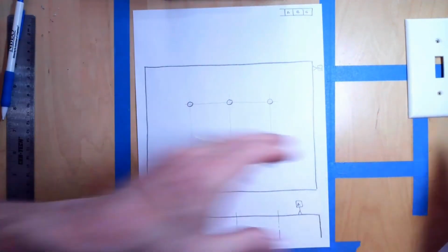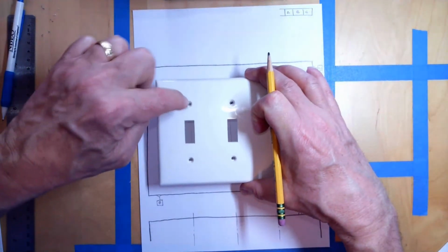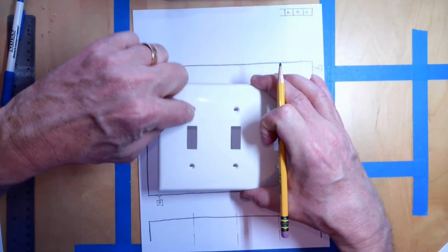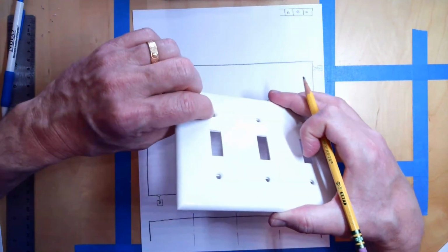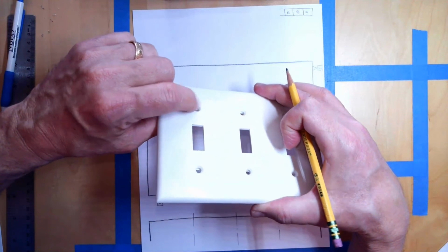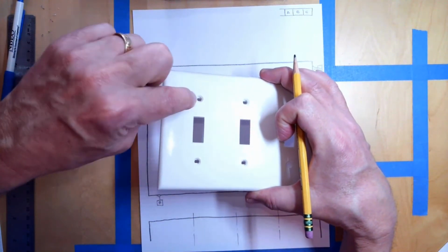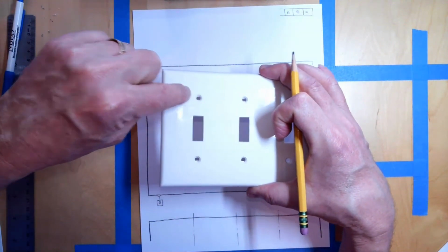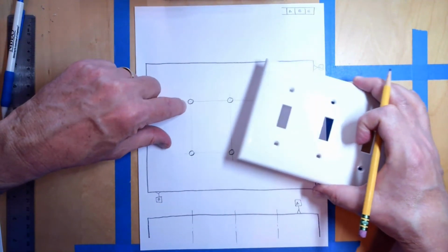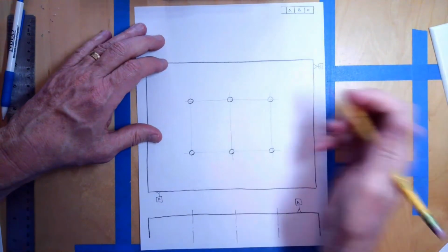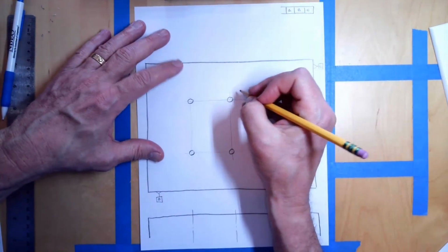Okay, A, B, C. Now, let's work on the tolerancing for the holes. These 6 holes are going to be tapped, because I'm going to have a screw that's going to go through here. This is a clearance hole. The screws go through the clearance hole. And in fact, you can see there's a slight countersink. So these are going to be flathead screws. Flathead screws are going to go through here, and they're going to thread into these holes. So these are 6 tapped holes.